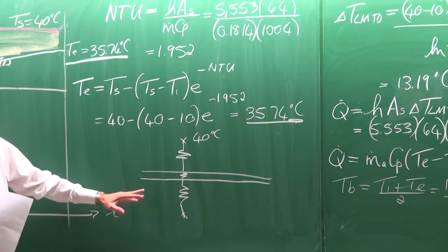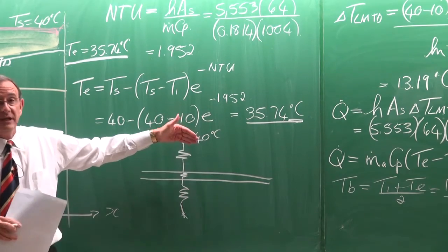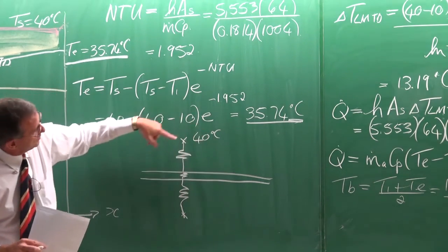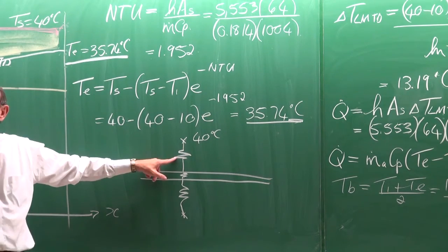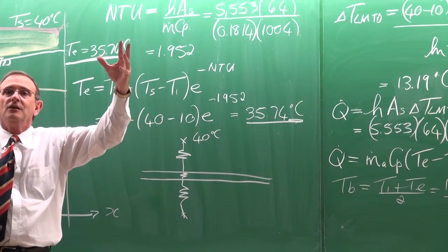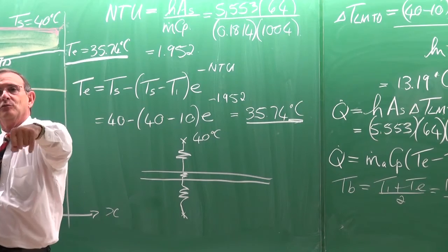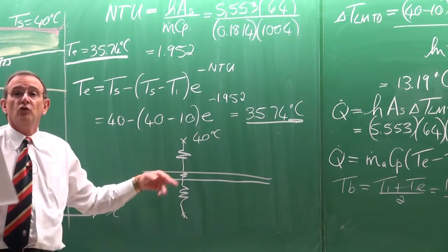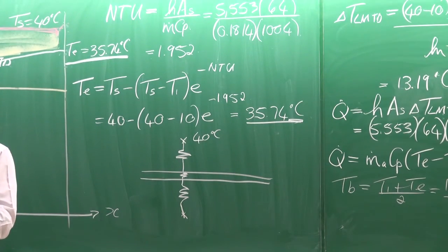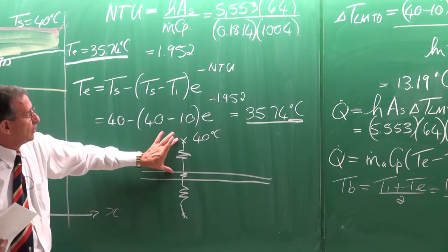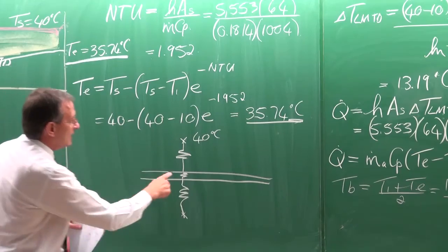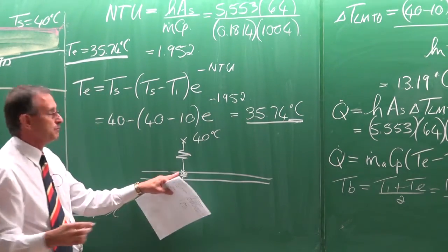Okay. So the correct thing in this case would be to take that temperature and get the heat transfer coefficient up there, which we're going to do in the next chapter. The heat transfer coefficient for natural convection. You haven't done it yet. You can maybe in the meantime assume a value of 10. Okay. Then you can calculate that resistance, and then you can actually calculate that correct temperature there.